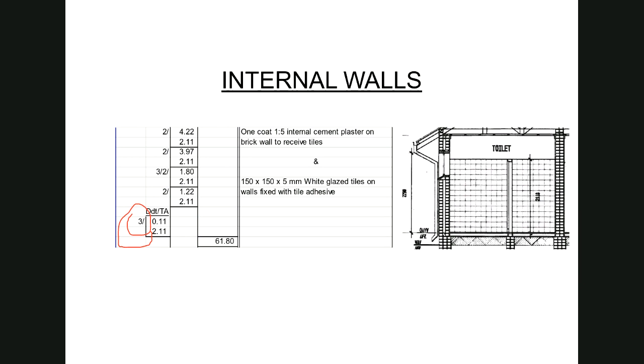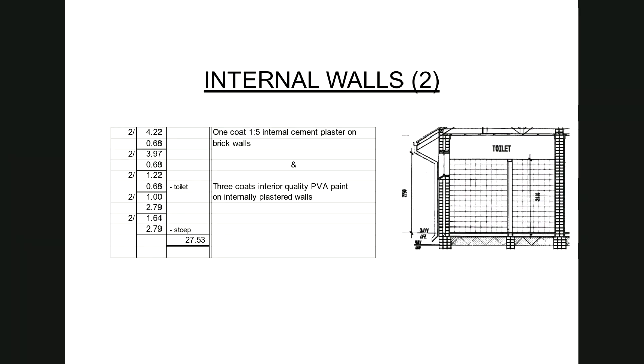So that deals with the plaster underneath the tiling. In the next item, I am now going to deal with the plaster that is actually painted. So I need to do a side cast over there, the 2.79 minus the 2.11, and I would get to the 0.68.